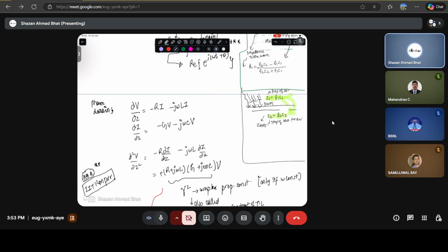As a result of which, some of the waves get reflected. Not some, in this case most of the waves get reflected. Most of them reflect. And that reflection is basically denoted by something called the reflection coefficient, R, which is Z1 minus Z2 divided by Z1 plus Z2. Okay, so this is the reflection coefficient.